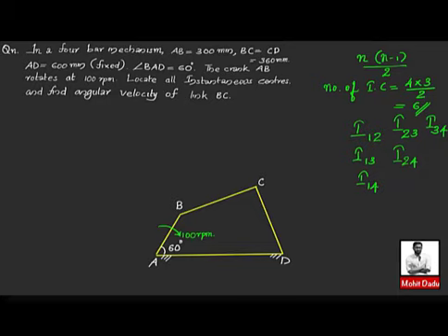So here in a similar way, you have to name these links also, number the links also. This is first link, and this is second link, this is third link, and fourth link. So you'll be locating these instantaneous centers. This link 2 is having a pure rotation about this point A. So the instantaneous center of rotation between links 1 and 2 is located at this point, and this point will be giving you the instantaneous center of rotation I12, that is between links 1 and 2.